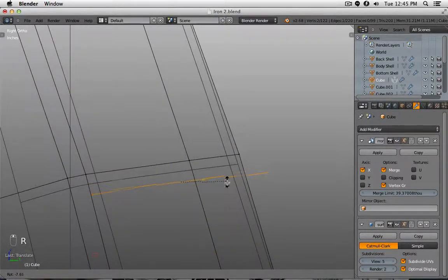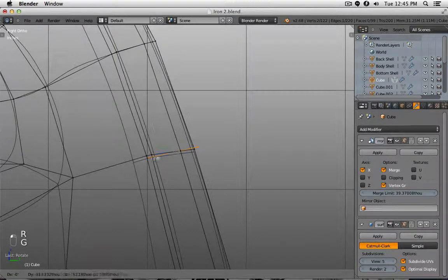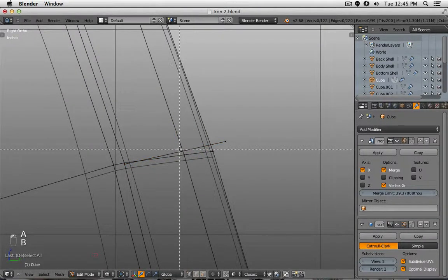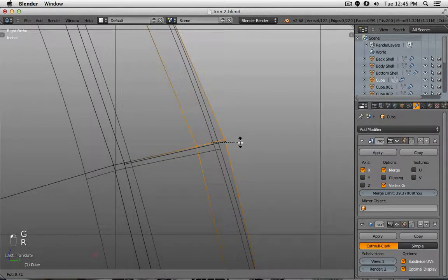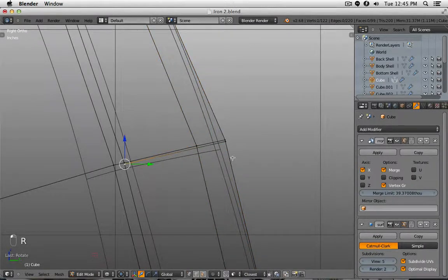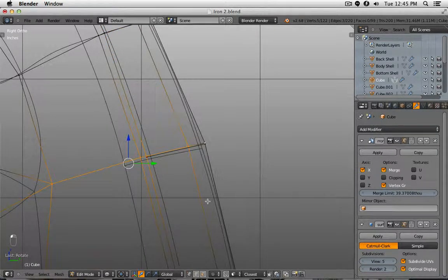And the nice thing is, because I only have 2 points, so 1 line, I can also use this line to maybe line it up with the rest of the geometry of my model to maybe correct some distortions or the way the geometry or the topology flows. So you see, I did not only change the way these points are positioned away from this edge, but also now these points are a little bit more in a nice line.